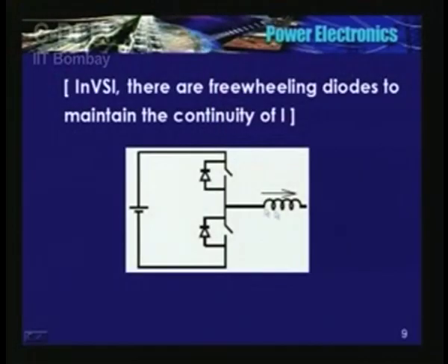See here, the inductive load in a VSI, you could have an inductive load. I am not saying that we are changing the current in an inductor instantaneously by opening the switch. In fact, we wanted very fast switches here. The moment I open the switch, I don't need to close this, current will start flowing through this diode. That maintains the continuity in a VSI. Okay.